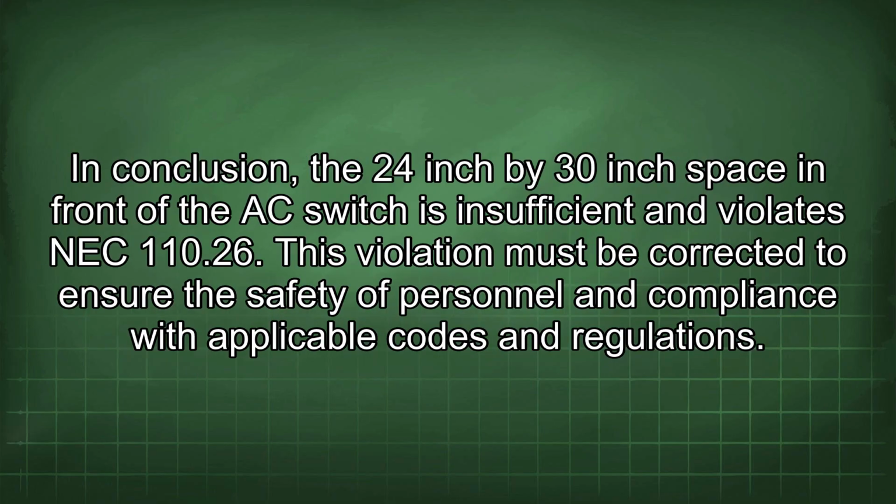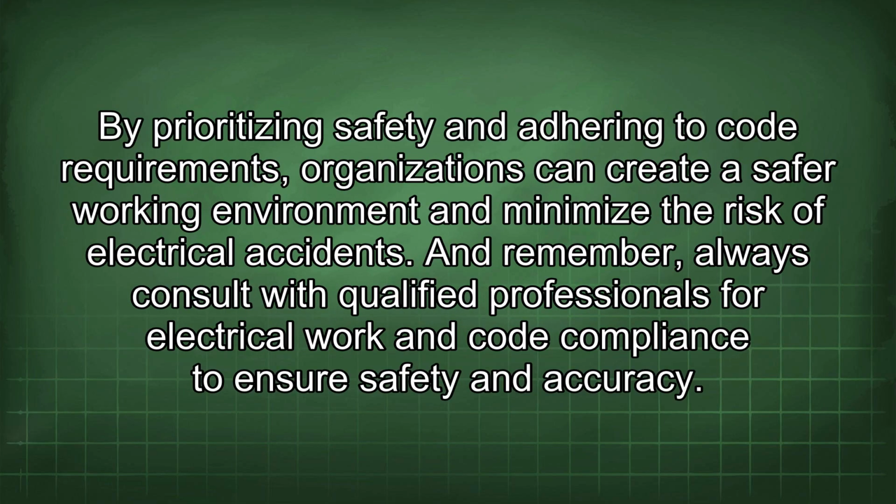In conclusion, the 24-inch by 30-inch space in front of the AC switch is insufficient and violates NEC 110.26. This violation must be corrected to ensure the safety of personnel and compliance with applicable codes and regulations. By prioritizing safety and adhering to code requirements, organizations can create a safer working environment and minimize the risk of electrical accidents. And remember, always consult with qualified professionals for electrical work and code compliance to ensure safety and accuracy.